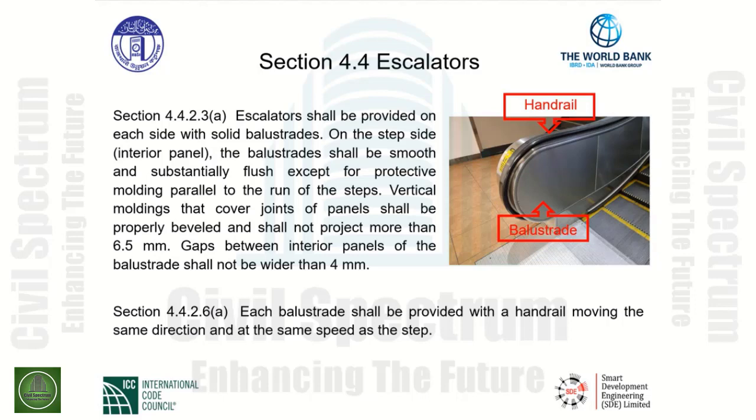Vertical moldings that cover joints of panels shall be properly beveled and shall not project more than 6.5 millimeters. Gaps between interior panels of the balustrade shall not be wider than 4 millimeters.